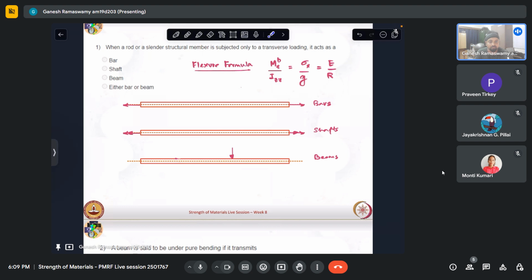The purpose of the bending moment diagram is, given a section, if I want to find the stress there, I should have some way to immediately pick out what the bending moment is at that point, which is what we essentially do using bending moment diagrams. So we have seen elaborately how to draw these. Here we will be looking at how to calculate our stresses and essentially curvatures.